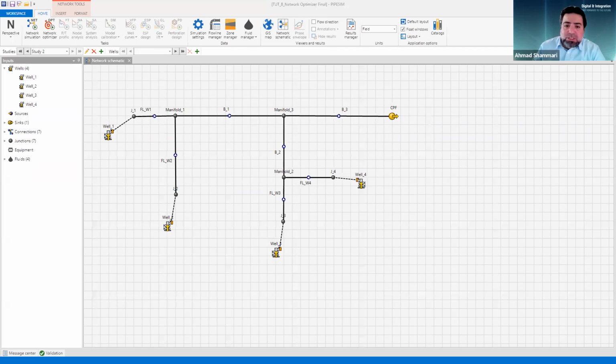So the number of nodes, if I am in the GIS canvas, all right, if there is a straight line, you just need to put two GIS nodes. If there is a deviation on the 2D, you need to put nodes, basically, because between two nodes, it's going to be a straight line. Okay, so it really depends on the curvature, the 2D curvature, okay?